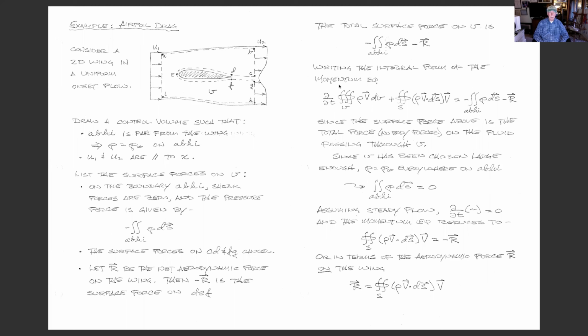They came out with an airplane in, I'm going to guess, '95 maybe, called the Sonic Cruiser, where instead of carrying a whole bunch of people, it would fly at 0.95 Mach number. All the subsonic transports were flying at, I think our airplane, a DC-10 or an MD-11, 0.84 cruise Mach number.